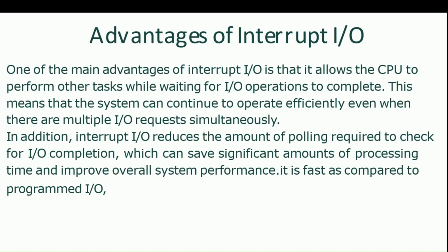In interrupt driven data transfer, whenever input output is ready for data transfer, it will interrupt the CPU. In the ISR, the CPU will perform the data transfer. This method is better than polling because here the CPU does not have to waste time in checking the status of the input output device.